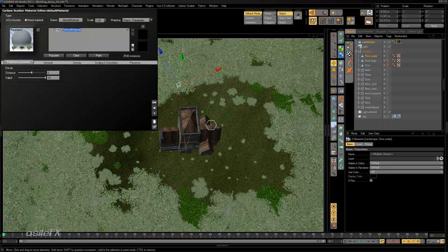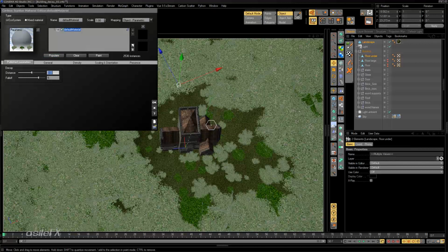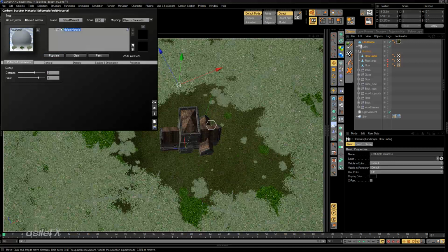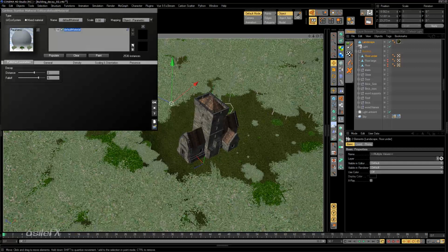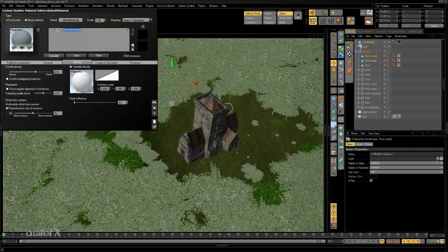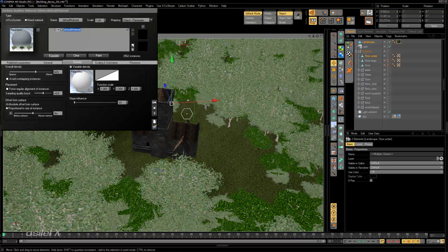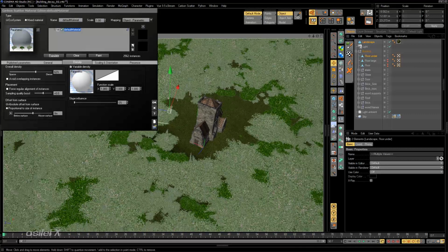So we could do 0 to 19, see something pretty gradual. 15 to increase that. If we go to 5 meters, the falloff is very sharp. If we want to raise that back, or pull it back, we can do that too. We can get a lot more control by stretching out the floor under the object, or whatever we have underneath it, to control this. Now if we go back and also change the density, we can have a mix of smaller objects and also the density change.